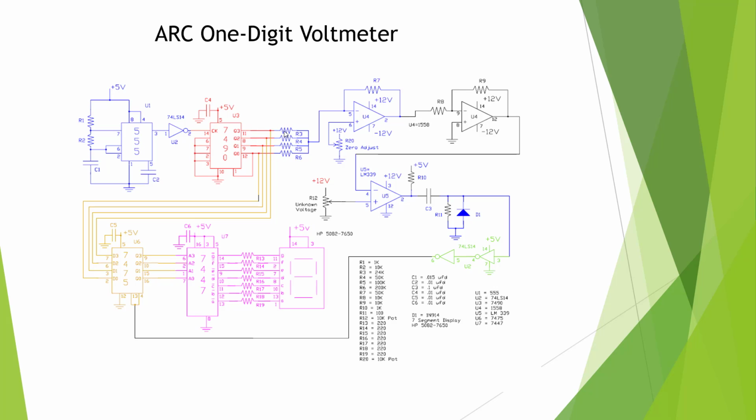And we have our binary weighted resistors fed into an op-amp. So this is our binary weighted summing amp. Here we have an adjustment so we could zero the output. Here we're going to have a negative going stair step. We're going to go through a unity gain stage based on the same size resistors, so we're going to make a positive going stair step. So our first test point is going to be a positive going stair step 0 to 9.